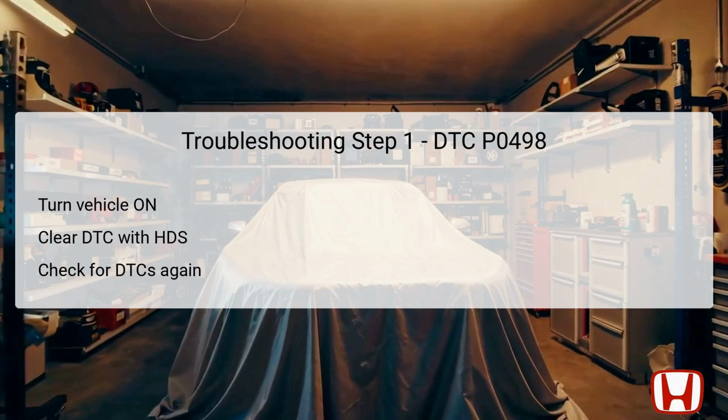The first troubleshooting step for DTC P0498 involves starting with the vehicle in the on mode. This means that the vehicle's electrical systems should be activated without actually starting the engine. The next step is to utilize the Honda Diagnostic System, HDS, to clear the DTC from the vehicle's memory. Following this step, it is crucial to check again for any existing pending or confirmed DTCs with the HDS.